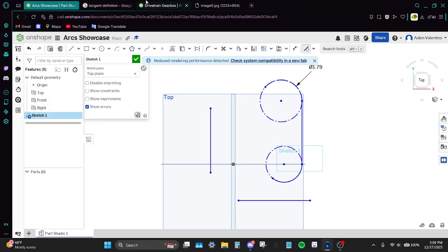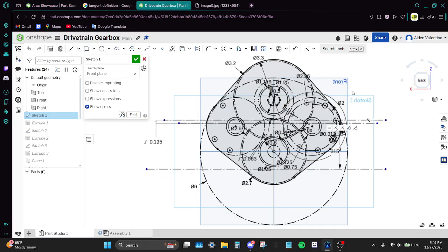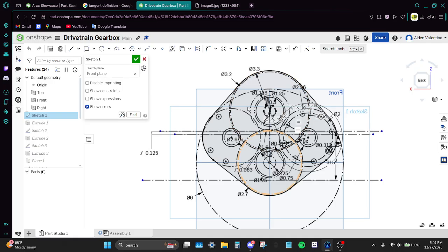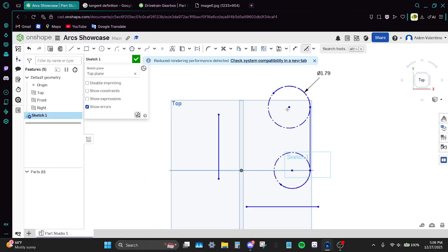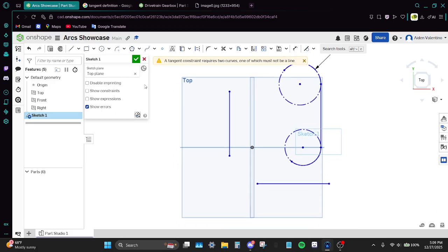This is really helpful for designing things for belts, or obviously right here, designing a plate around the motor mounts and the wheels and gears. These basically start at one center point. If you have a defined center point that you wanted to make an arc around, it's really helpful. For our fidget spinner from our last day, you probably had to use a center point arc from where those bearing holes were. Really helpful with that. Moving on to our final arc.